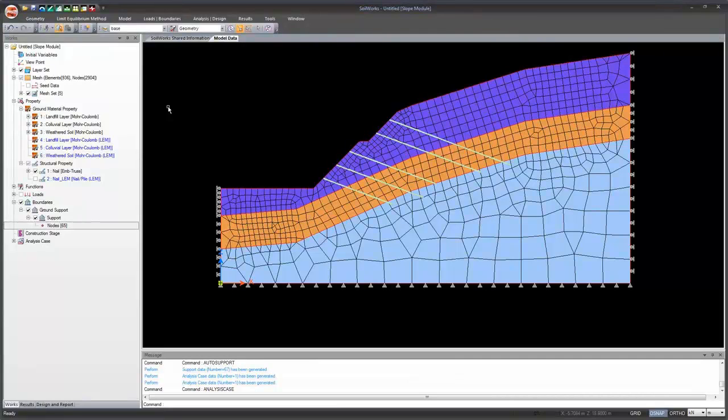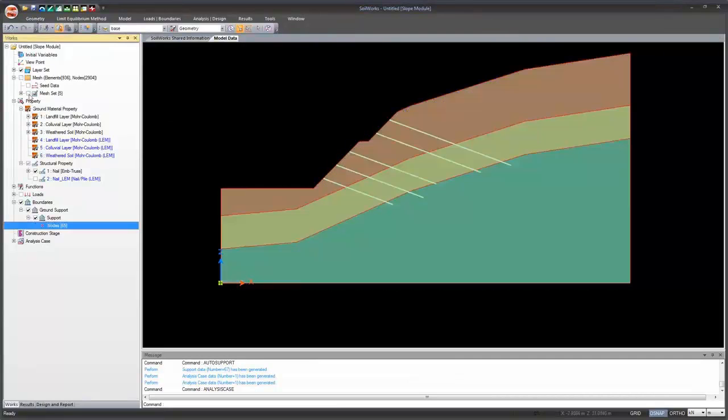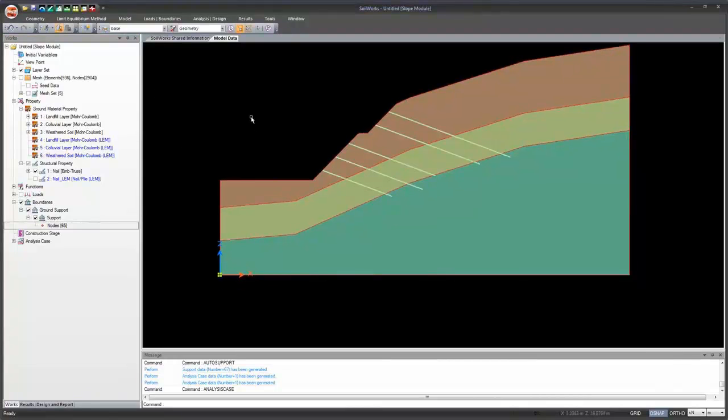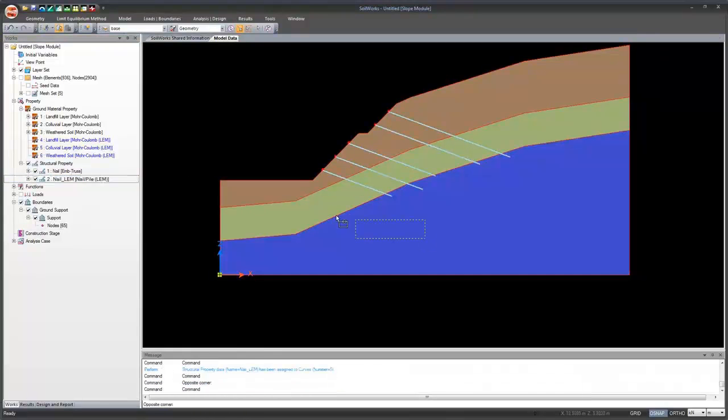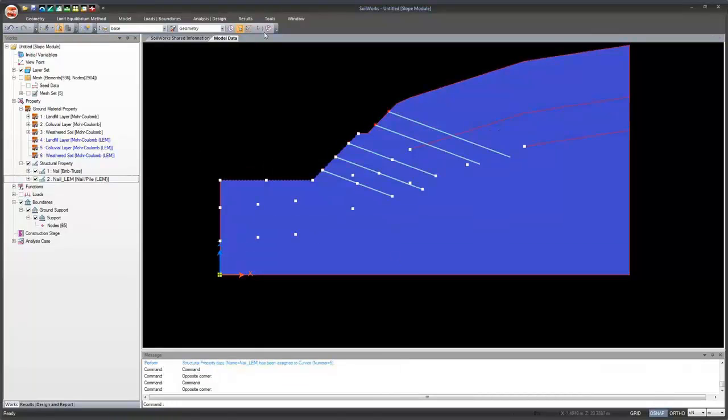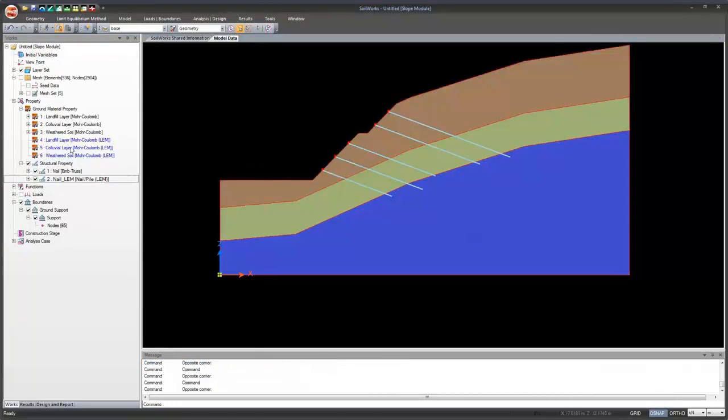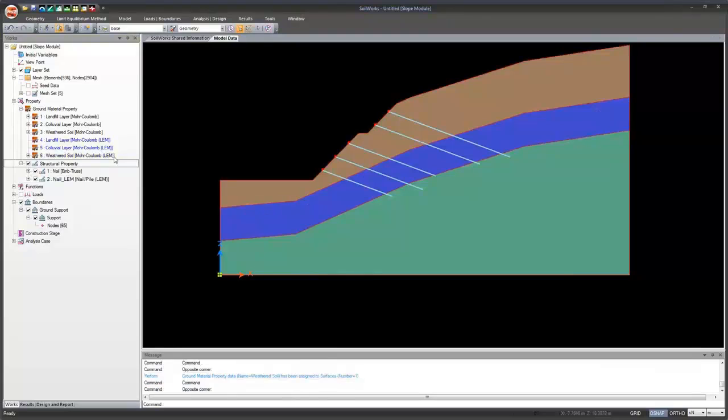same model. So just go to the mesh set and just click uncheck. So it is unchecked right now. Now once again we have to assign the properties. So property assigning is similar to what we did. Just select the curves for the nail and just drag and drop it. So it's assigned. And similarly for the ground surface layer, sorry, just unselect all, just select, drag and drop.